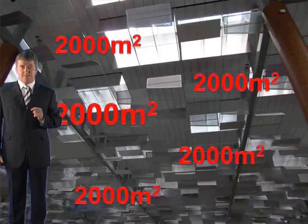The first thing to determine is the number of reservoirs that you're going to have in your building. You need to determine, first of all, how many reservoirs. Now, again, for cost reasons, you would like to have the minimum that meets the design criteria. You don't want to put reservoirs in for no reason. The limit to the size of a compartment, a reservoir, in a natural ventilation system is 2,000 square metres.